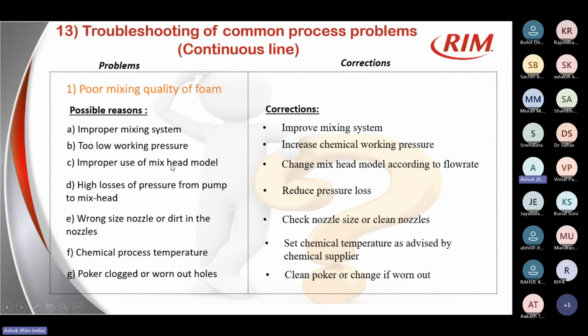The possible reasons can be an improper mixing system, too low working pressure related to the iso and polyol pressure at the mixing head, improper use of mixing head model, high pressure losses from the pump to the mixing head, wrong size nozzles, improper chemical process temperature, or the poker is clogged or worn out. So these are the possible reasons for poor mixing quality of the foam.